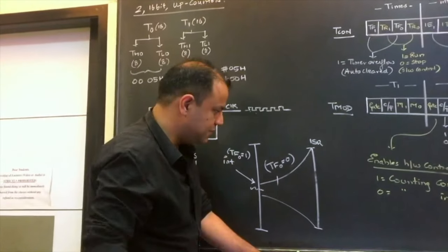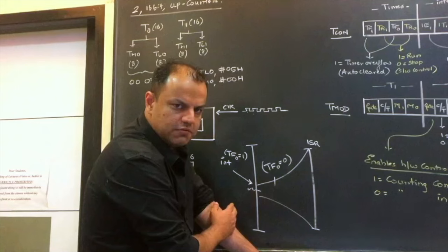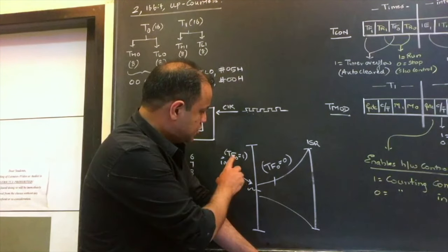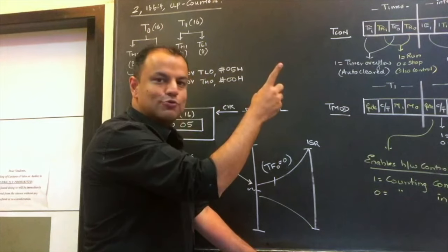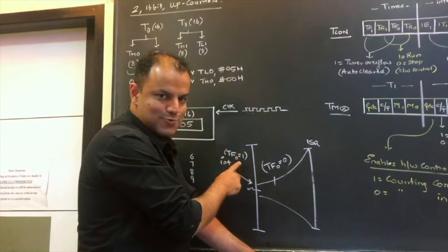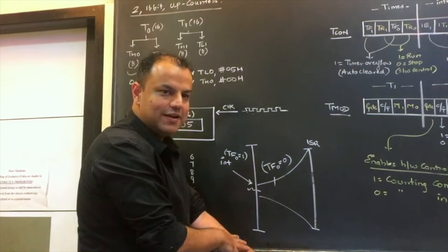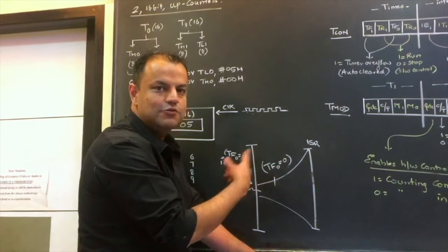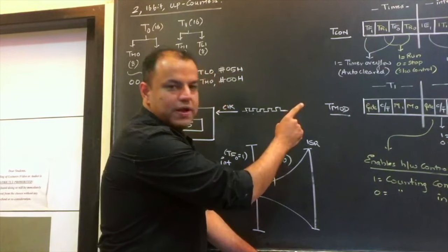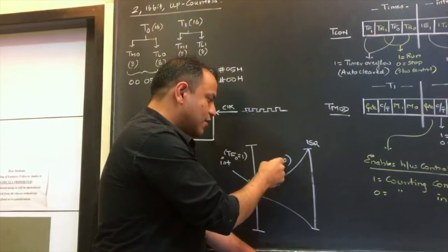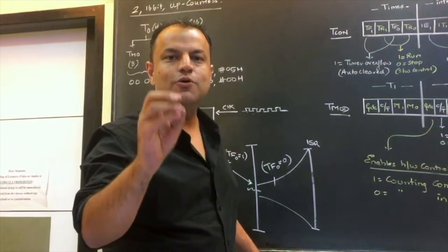So my point is, when you finish the ISR and come back to whatever program you were doing, should this flag still remain 1? No, because we went to the ISR because the flag was 1. If after coming back the flag is still 1, obviously we will get the interrupt again, we will go to the ISR, and this will become an infinite loop. So instead of that, while going to the ISR, this flag automatically becomes 0. Which flag? The timer overflow flag.